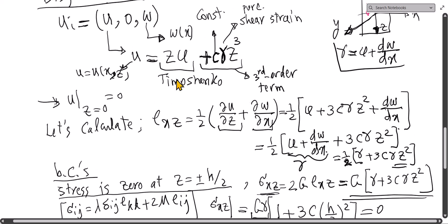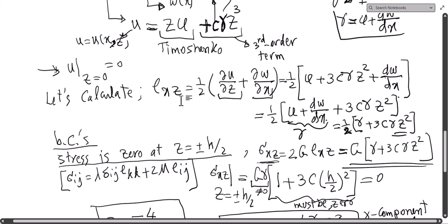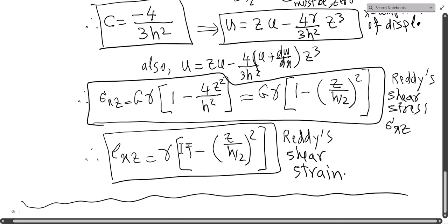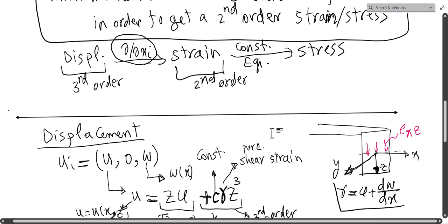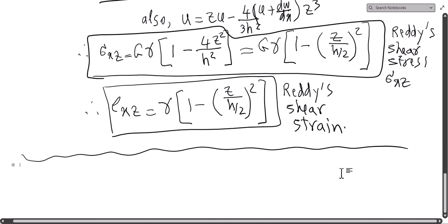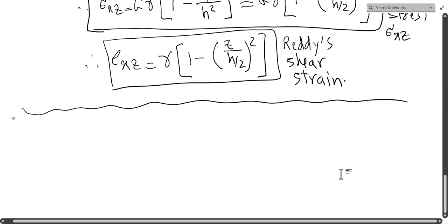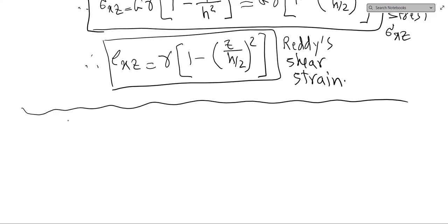We mentioned that having a third order polynomial for displacement u will give us the correct form of the stress and strain, the correct being the compatibility of these quantities with the boundary condition that we have on the top and bottom, assuming that there is no stress there. Okay, so let's continue with calculating the full strain to